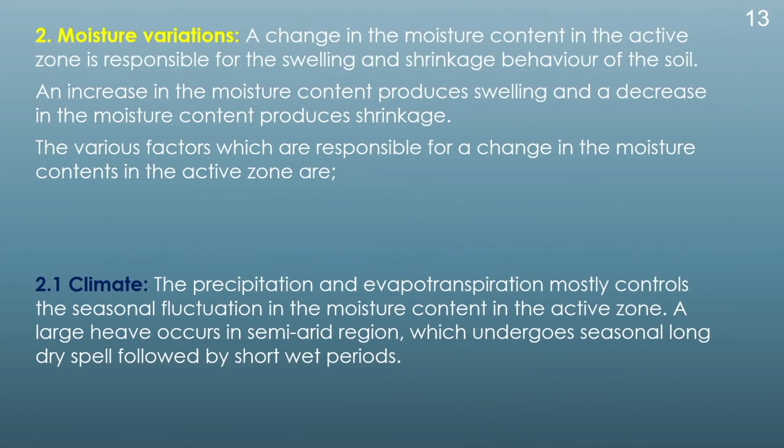Next comes the moisture variation. A change in the moisture content of the active zone is responsible for the swelling and shrinkage behavior of the soil. This we have already learned from our previous classes. So, any change in the moisture content in the active zone also changes the swelling and shrinkage behavior of the soil. So, the various factors which are responsible for change in the water content in these active zones, we will go one by one.